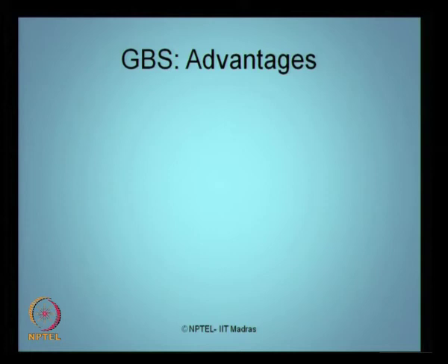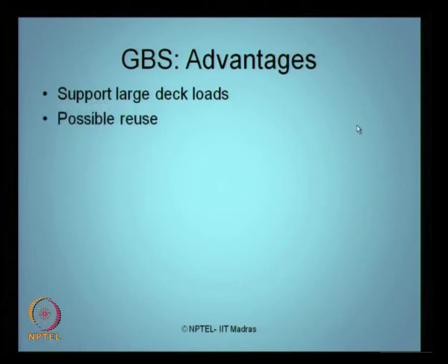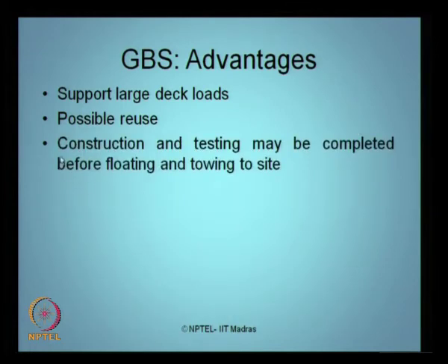Gravity based platforms have many salient merits in offshore drilling. They support large deck loads. They have a very high possible reuse of the material. The construction and testing of these kinds of platforms are generally completed before they are floated and towed to the site. So, there is a good amount of quality control in construction, and inspection can be done before the platforms are actually installed at the site.